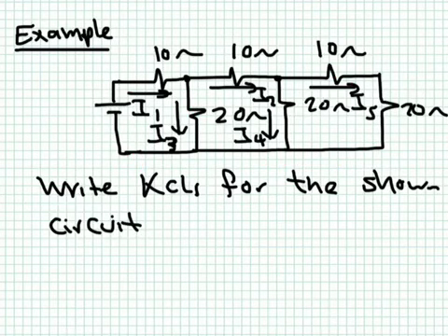And in many electric circuits, we simply take this one as our ground. We say we're going to arbitrarily give it a zero voltage. Remember that all voltage differences are relative, so you're only measuring the voltage difference between two points. So you can pick any point that you want in your circuit and call it ground. You say, I'm going to call this one ground, and everything is going to be relative to this one. So in this circuit we have three nodes.